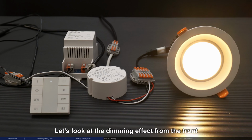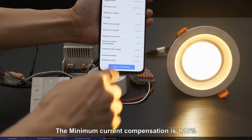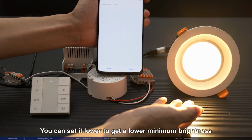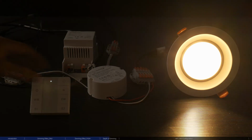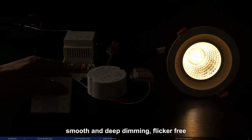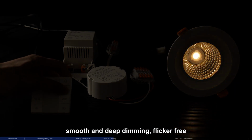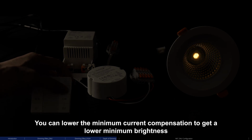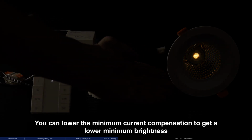Let's look at the dimming effect from the front. The minimum current compensation is 1.18%. You can set it lower to get a lower minimum brightness. Long press to reduce brightness. Smooth and deep dimming, flicker free. It's at minimum brightness. You can lower the minimum current compensation to get a lower minimum brightness.